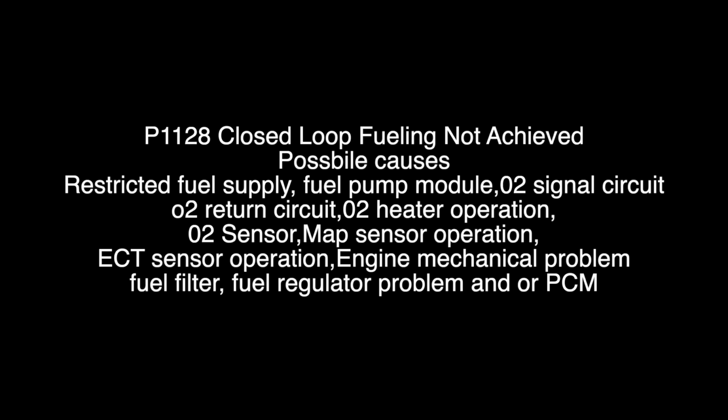So the similarities between the two codes seem to signal towards the O2 sensor itself or the electrical wiring. So this is where we're going to start and troubleshoot.